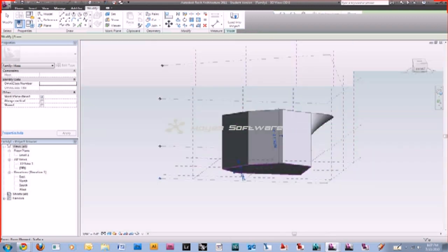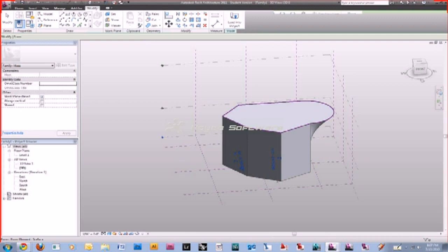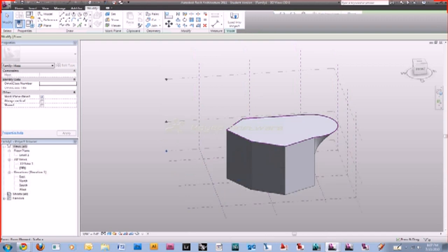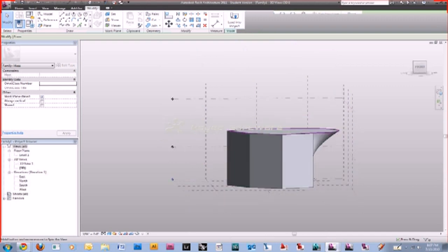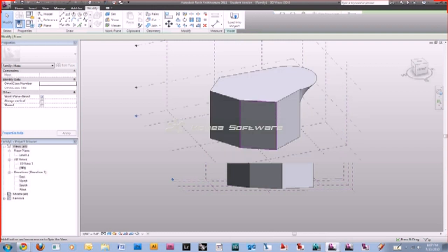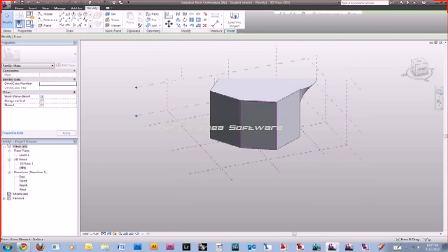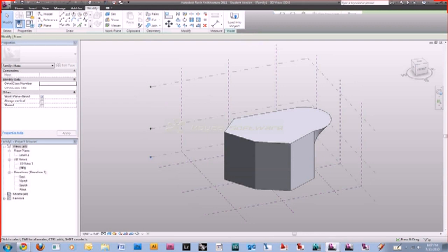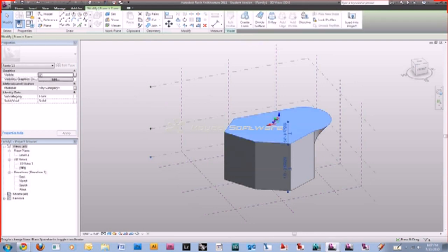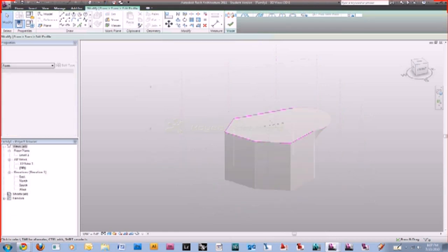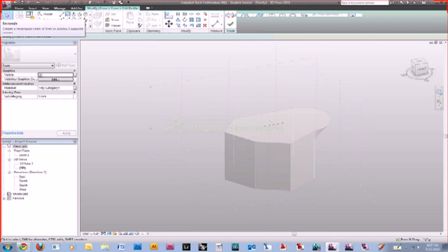Profiles are only horizontal to the horizontal plane you drew them on. So if you drew that extrusion at first on a vertical plane, then the profile is going to be vertical, and then the edges will be horizontal. So you have to know where the object came from in order to actually edit it. So now I can select this face, this horizontal face, and then I can go to edit profile, and it'll show me what makes up that shape. Then I could easily just delete this, or even delete the whole thing, and then go to a new drawing tool like a rectangle. Too fast still?